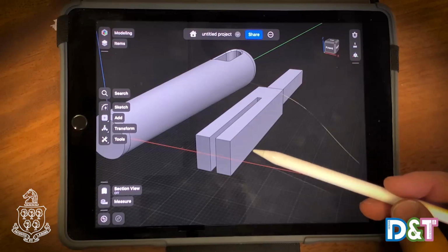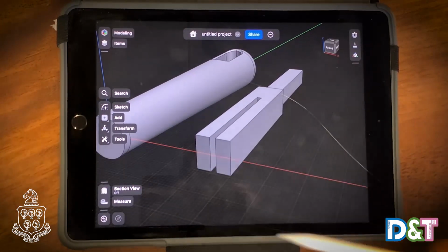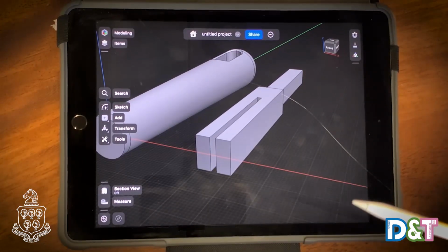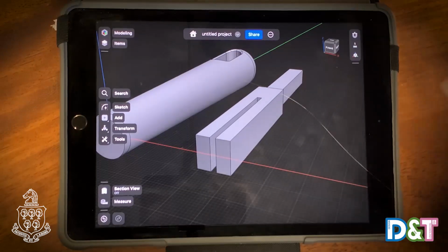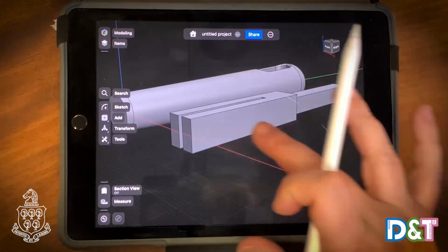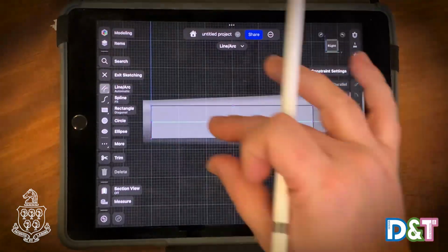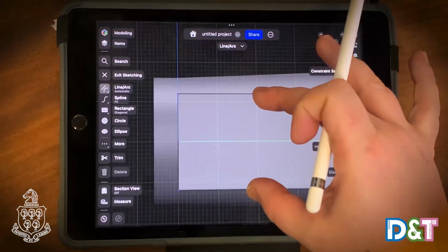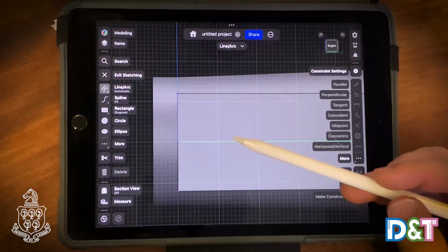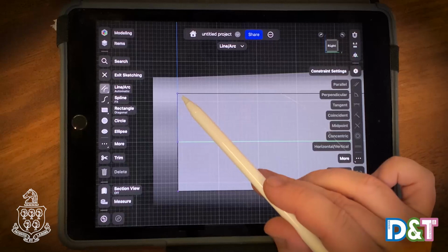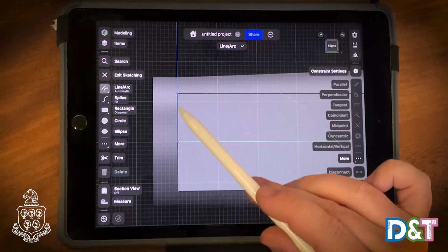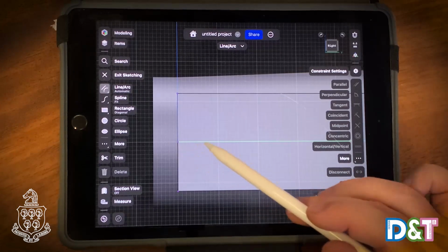Next, with this shape, we're actually going to do the through hole, which the pin goes through and holds the blade all in place. So we're going to double click on this surface just here, zoom in a little bit. And I know this hole is going to be the center point of the circle is going to be 6 millimeters from this end.